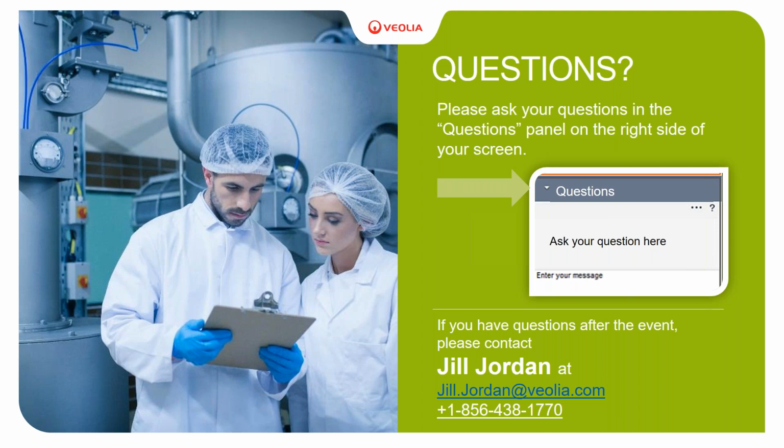Okay, so I'm a little confused, but I'll try to answer. First of all, it takes like 9 to 12 months to convert enough flock sludge to the granular sludge that you would need for a UASB system. And you would have to keep reseeding because the flock won't stay in at the higher upflow velocities seen in UASB and EGSB reactors.